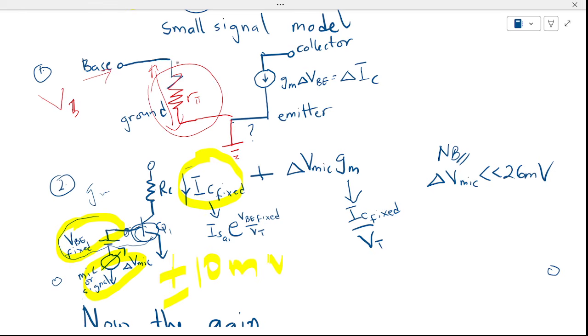And the voltage across this resistor, let's just call it V pi, would be the one affecting. We know that in this particular instance, VBE and V pi are the same. So any change in VBE, the voltage I'm applying here, affects the collector current. And because we're only dealing in small changes here, there's a linear relation.